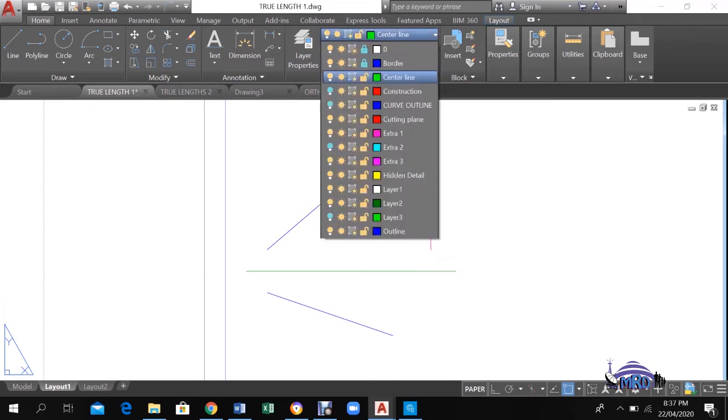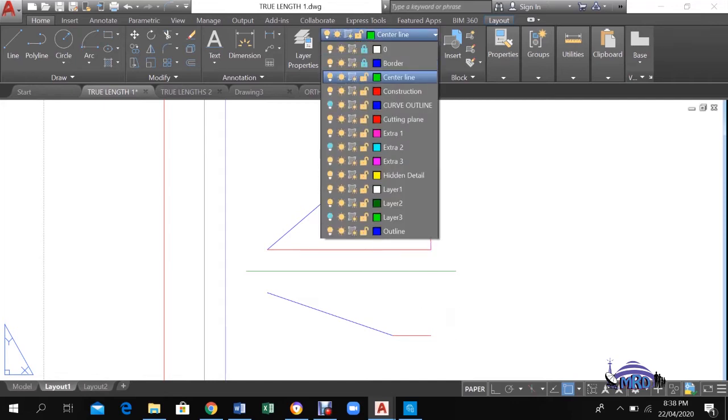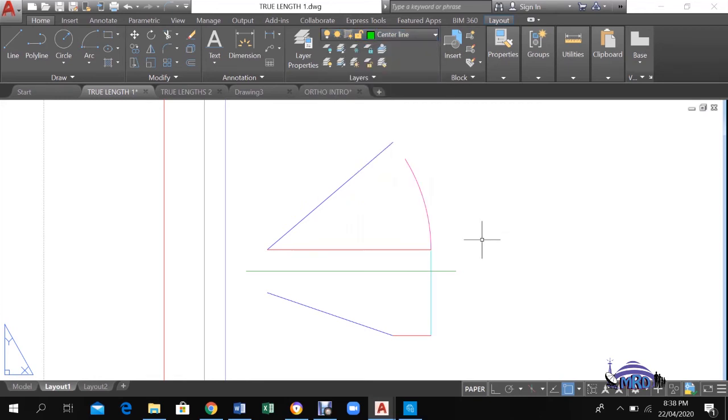Now, horizontal in this instance then would look like this, where you pull a line across to meet that curve, and on the plan for the corresponding corner, you will do the same thing, just pull a horizontal line across. The next stage in your construction will be to take a vertical line from the intersection here with your horizontal and arc down onto the plan. So if we drop that line now, then the construction looks like this, with this vertical line coming in.